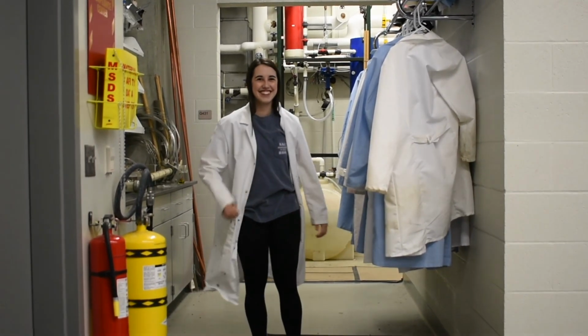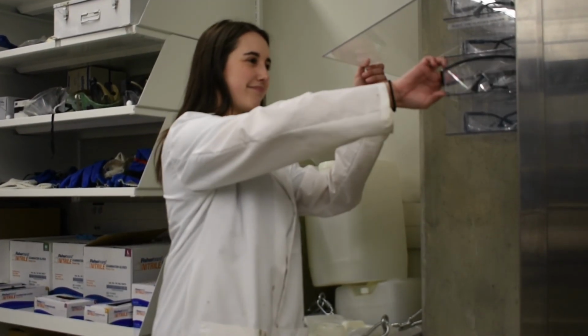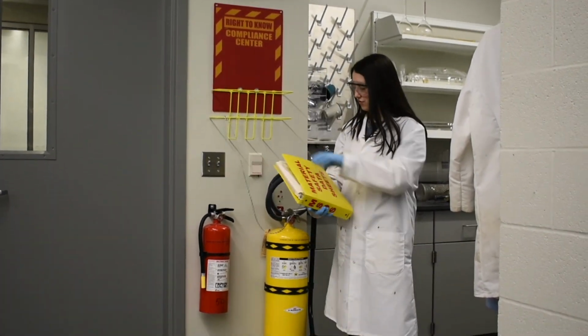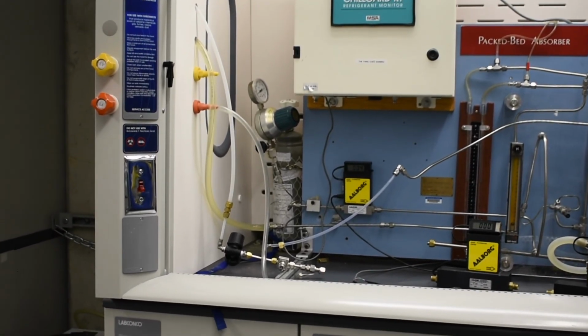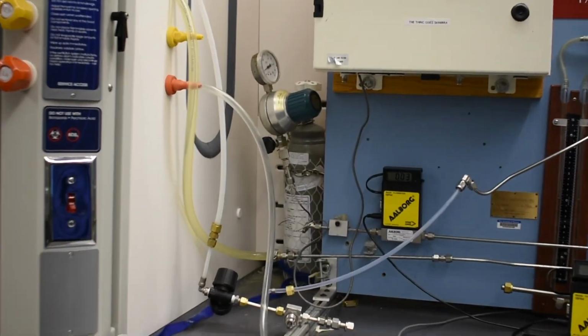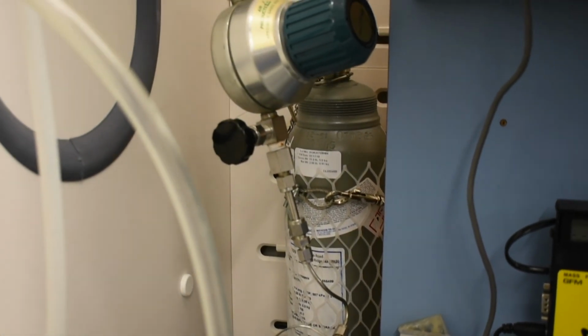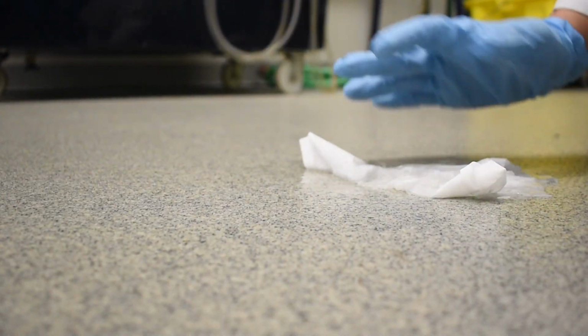For the absorption lab, proper protective equipment includes a lab coat, gloves, and safety glasses. Due to the use of chemicals in this lab, it is important to know where the safety shower and eye wash station are located. It is important to also note the location of the fire extinguisher and review MSDS sheets before performing the lab. The most significant hazard associated with this lab is the use of ammonia, a toxic and flammable gas. If at any time the ammonia gas is smelled, alert the instructor. Beware of any tripping hazards in the lab and clean up any water spills to avoid slips.